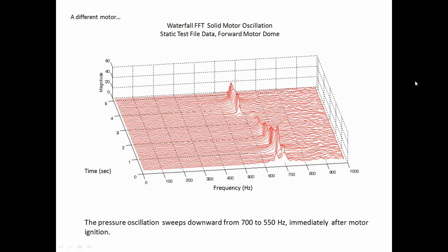And typically when we isolate avionics, the mounted isolation frequency might be down around 50 hertz, maybe as low as 20 hertz, which would be several octaves lower than the frequencies shown here. And if that were the case, then we could just ignore this data. It would be unnecessary to test an isolated component for that particular sine sweep that occurs.